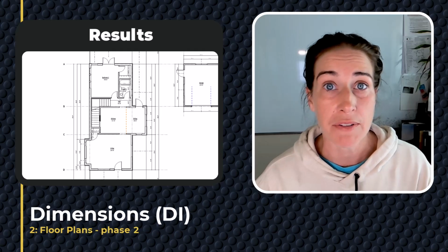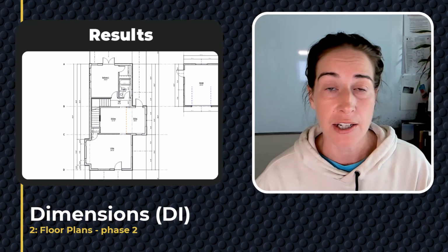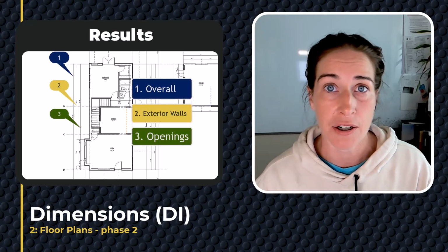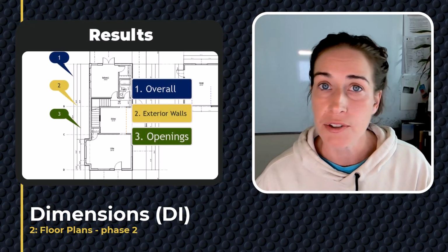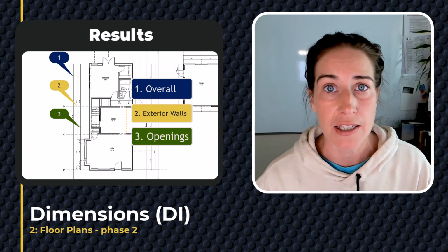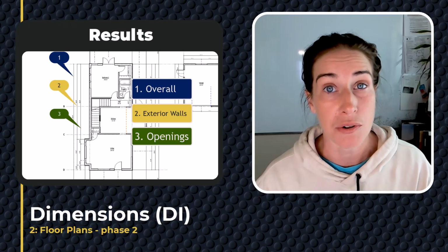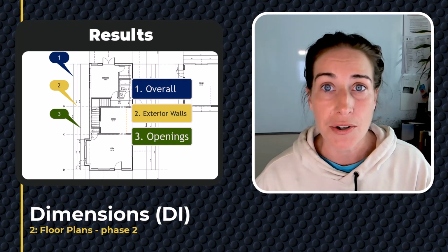As a reminder, in this video, we really use the power of dimensions in order to verify our design. We use the standard of 3 exterior dimension strings. The first for our overall building dimensions, the second for any exterior walls, and the third for all openings like doors and windows. We also added text to a dimension. I hope this helps.